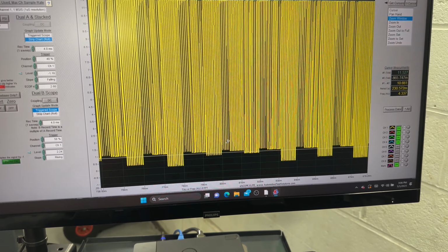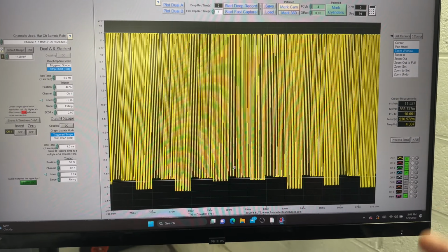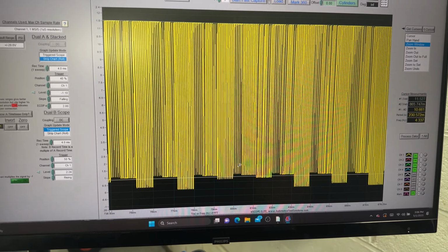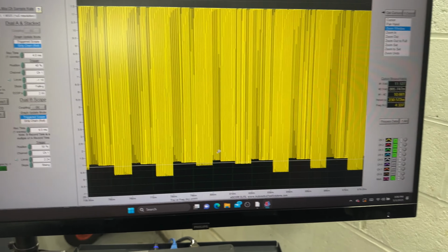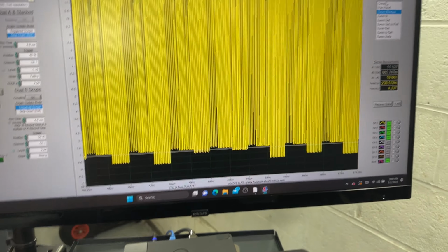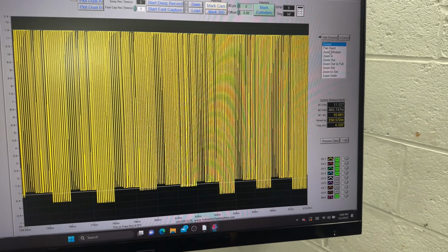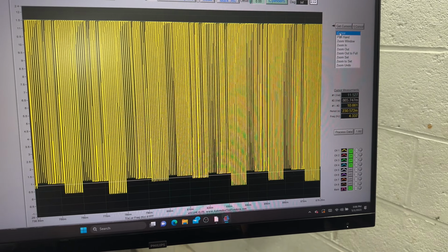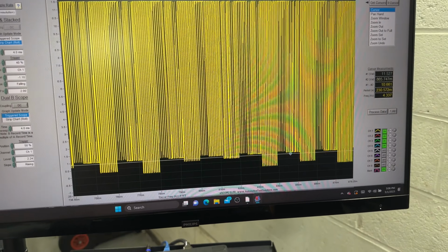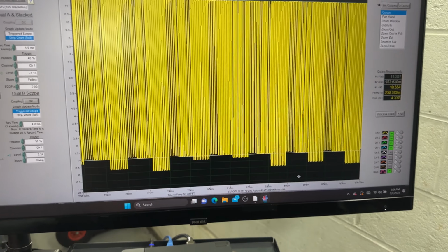Sometimes you want to have a little higher and a little lower so you can see the signal in its full amplitude and do an analysis. This is what I like to do. Because then you can get the cursors, and with this scope you need to select by hand where you're going to use them in the window. If you want to move the cursors, just select the cursors in there. So now I'm going to put them more accurately where we are.